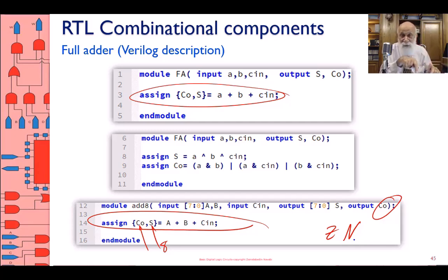Remember that these adders are adder subtractors, meaning that if you have two 2's complement numbers, they're going to perform fine. If you have a positive 2's complement and a negative 2's complement, this is going to work perfectly. So it is really a 2's complement adder.